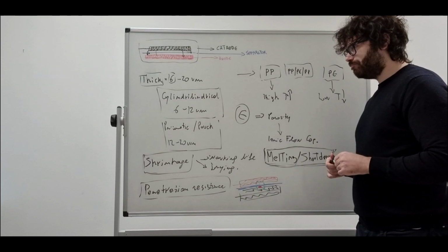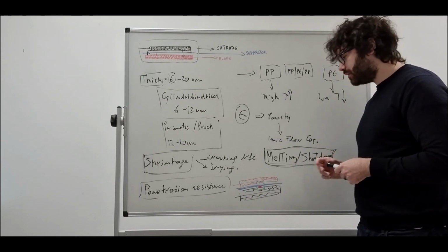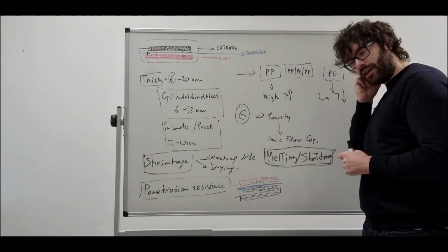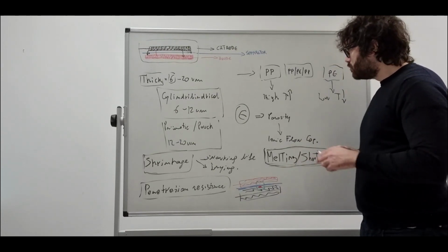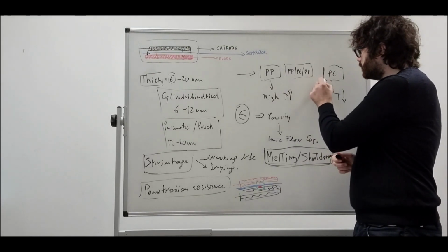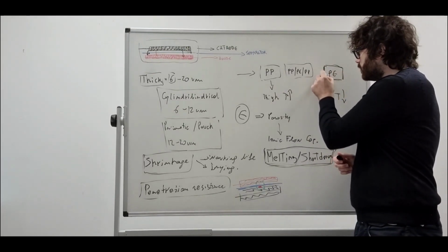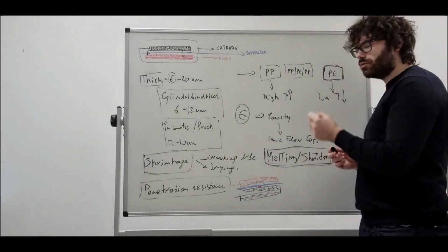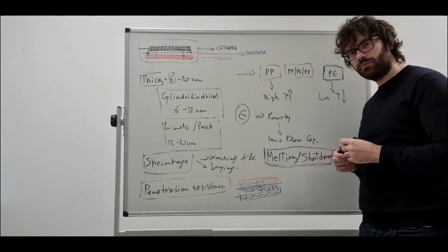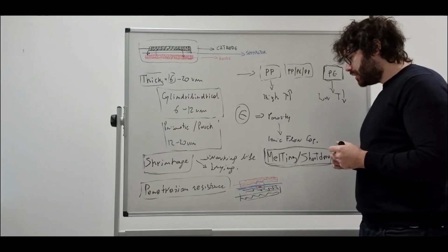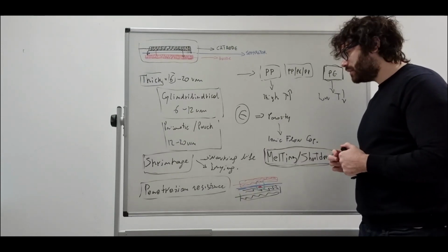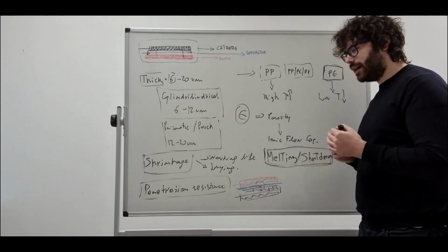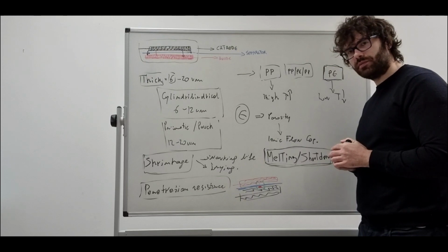which is triggered by the temperature. Okay, when the temperature is high enough to melt, for example, to melt down the PE, the polyethylene will close the micro and nano pores of the separator, shutting down the cell and avoiding any kind of ionic flow through the separator itself.